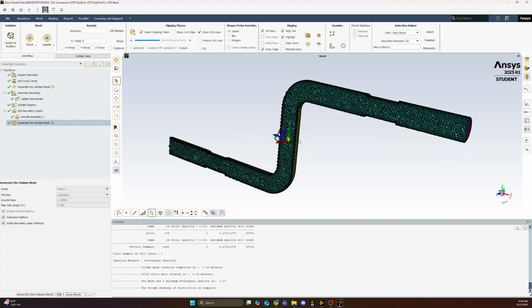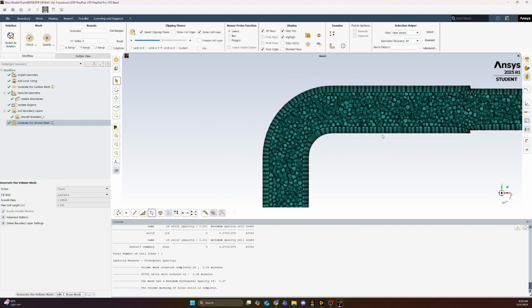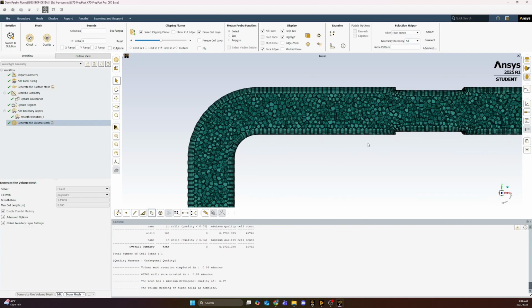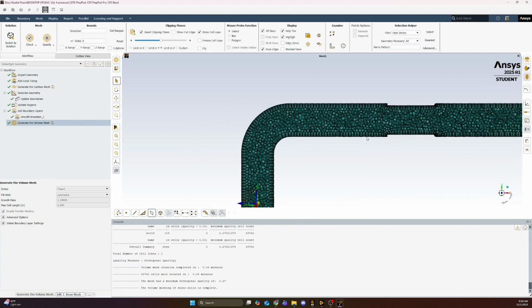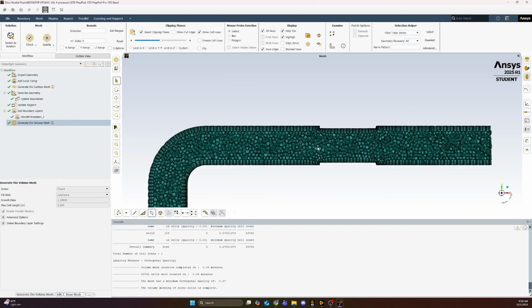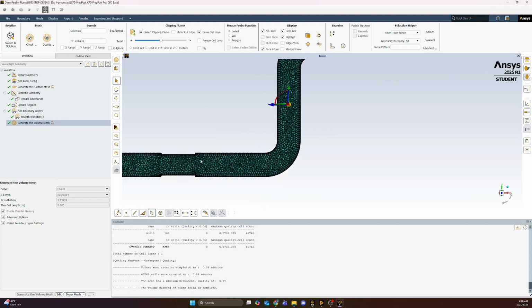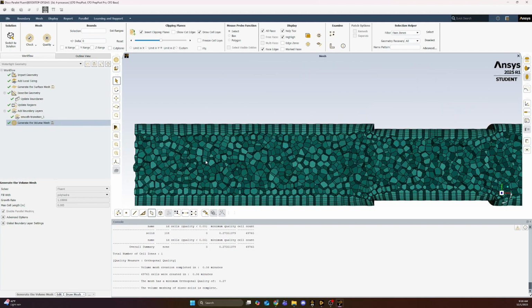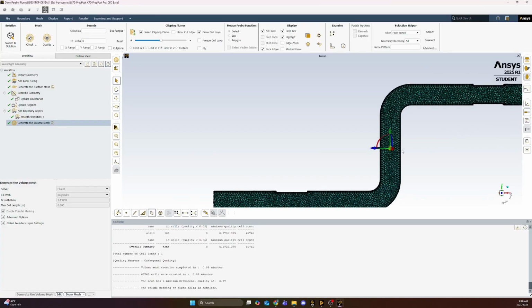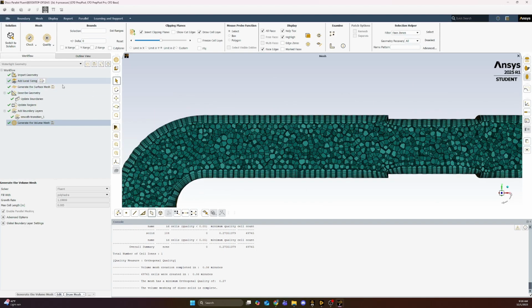Okay, now that the mesh is generated, we can kind of look at it and see if this is what we want. We're not doing anything too crazy. If you're doing this for a really intricate system or maybe some kind of volatile or compressible fluid, you might need some more refinement than this. But this is quite good. We ended up with 70,000 cells, and I think for the purposes today, this will be okay. And I will discuss more how to validate these results later, because potentially maybe this isn't enough mesh, but we can find that out later.